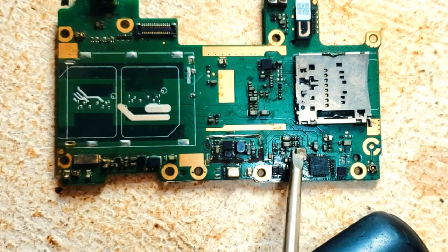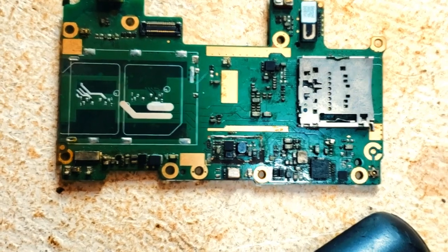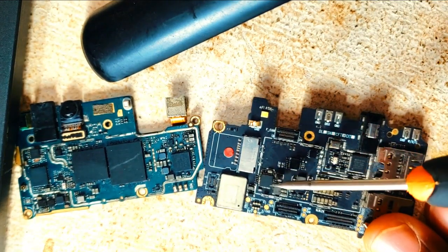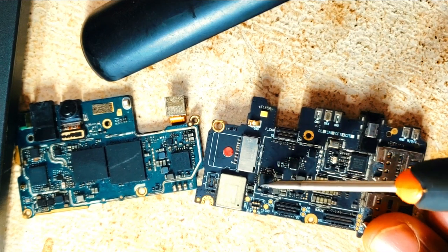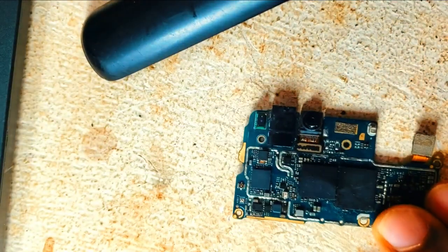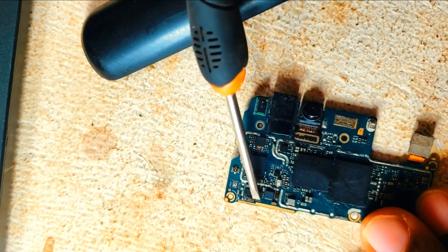If the charging IC is bad, the phone will not charge properly or may not even charge at all, even if you speak in tongues. If the phone's charging IC gets a short circuit, the phone won't be able to power on. Some shorted diodes in the power section can also cause power problems when they get shorted as well. Sometimes, a charging problem could be so complicated that you might start thinking that you have been sinning all your life and God is punishing you for that.